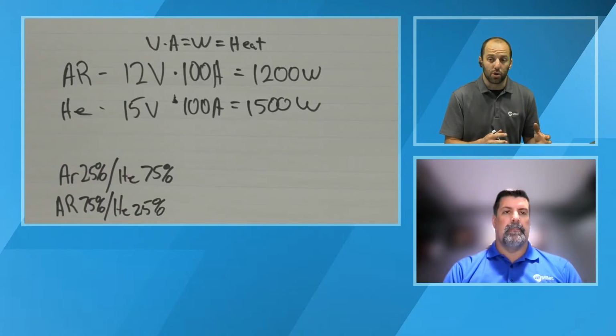Now, if you're doing short welds, you can get away with running that for a short period of time, maybe cheating the tungsten a little bit and running higher amperage than what it's designed for. But if you're doing longer welds, over 6 inches, and running, let's say, 230 amps on a 3/32 tungsten, you're going to start seeing some of that tungsten degradation. That's an indication that you need to step up your tungsten diameter, or you're going to be going through a lot of tungsten, and likely that tungsten could be transferring into your welding pool.